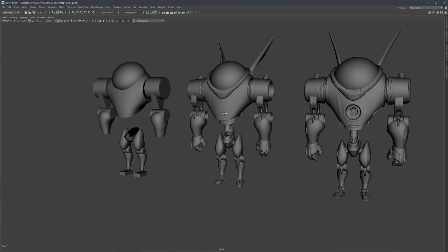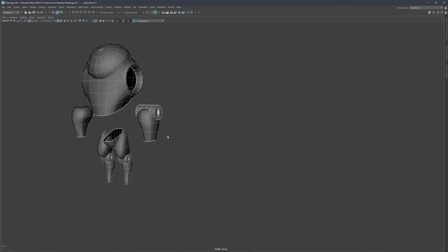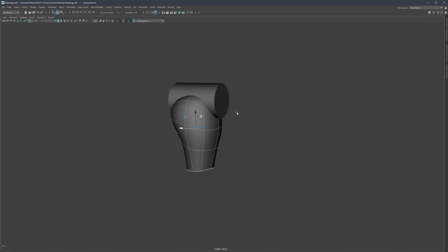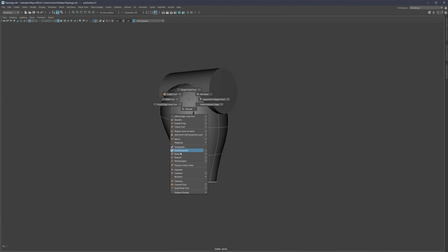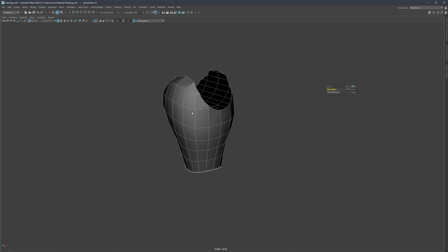So in our case here, if you come back to the drawing, this was just something like using a simple cube, subdividing the cube, and then from the cube I'm going to stretch this out and use booleans to break the cylinder on the inside. So I actually can extract faces. This started from a very simple cube, pushed out, and from that cube I created this form, and in the end, once they intersect, you're going to use boolean. So let's say we're going to have something like this, and once you use booleans and then use the difference, you're going to get this, and then it's going to be a matter of organizing and cleaning the topology.